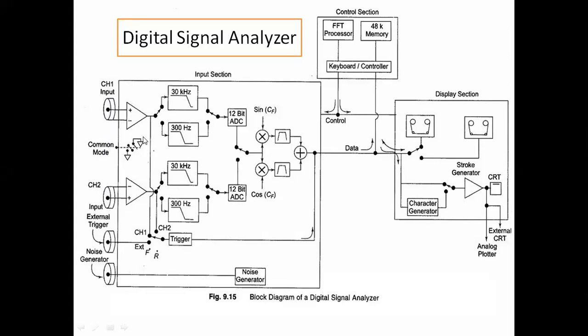So with that, we can find the similarities with the same signal itself only. Okay. Whenever we have to find the cross correlation, we can identify the similarities between two signals. So one signal is applied to channel 1 and another signal is applied to channel 2. So with this process we can obtain the similarities between two different signals.